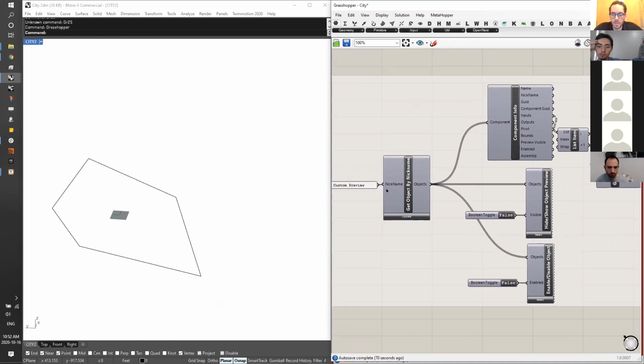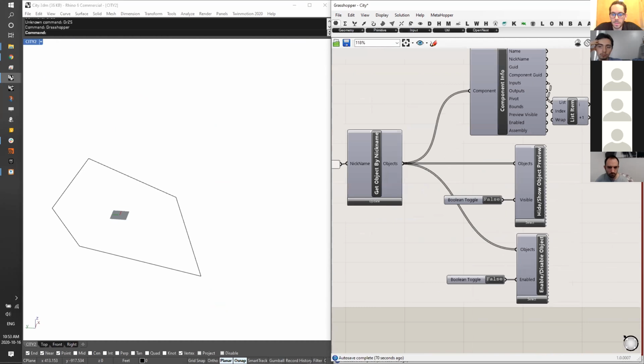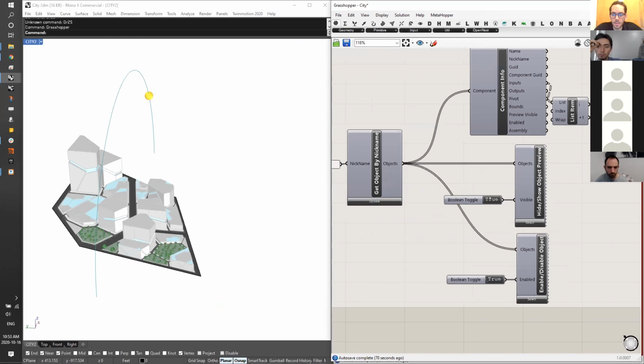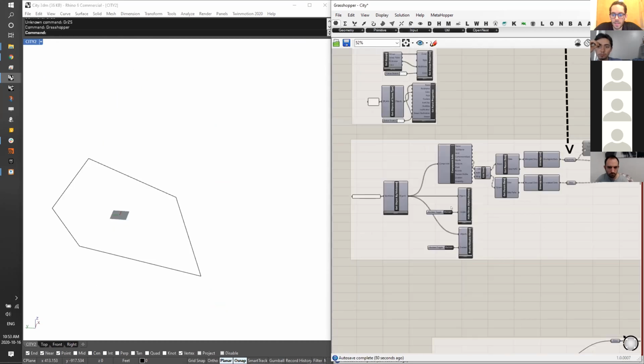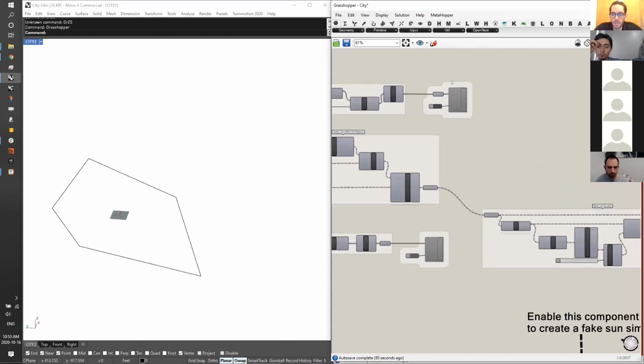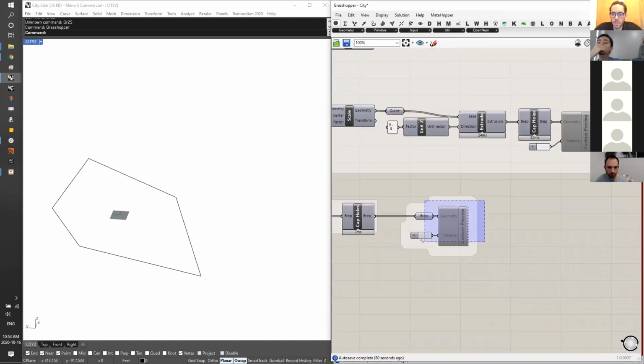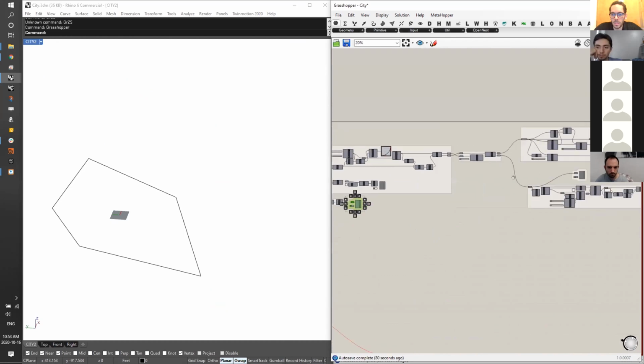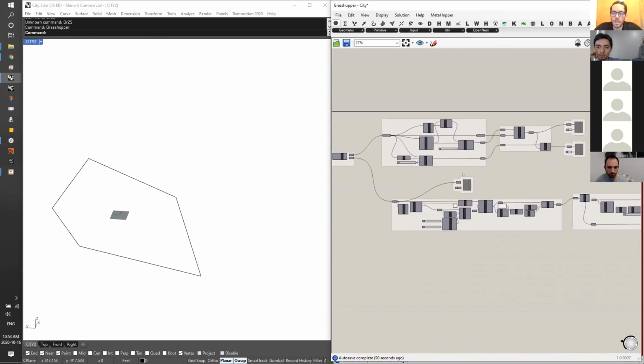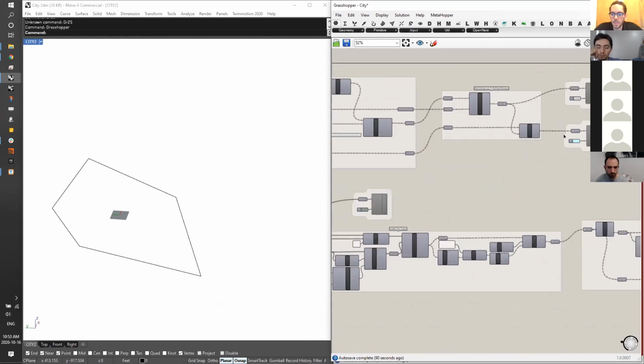You have to press the update component to make sure everything actually processes. But once you update everything, you can enable all your objects or disable all your objects. And if you look around, you'll see that all the displays have now been disabled. That's working remotely with Meta Grasshopper, or MetaHopper, to be able to affect all sorts of different components.